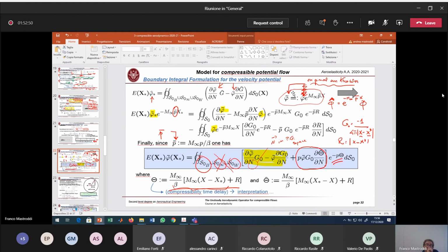But we study linear problem, and therefore the unsteady solution around any kind of steady solution is the same for the system. And therefore it's not essential to consider a deformed steady configuration for studying the stability. We study the stability at 0 angle of attack with no problem. I am repeating a lot of concepts for you. Important concept.